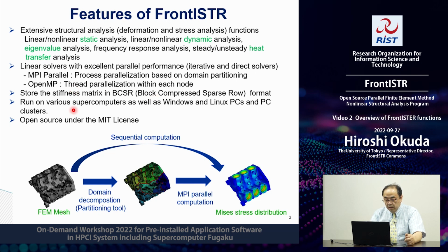The large-scale linear equation is called the stiffness matrix in the finite element method. Since the size of the matrix is very, very big, we need to compress it, or some sophisticated way should be introduced. In FrontISTR, the block compressed sparse row format is employed.